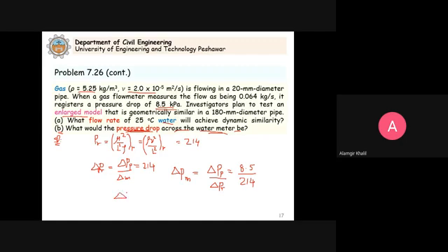So now this delta P, change in pressure for the model, this will be equal to 0.0397. So this is kPa, kilopascals, or this can be written as 39.7 pascals. So this is Newton per square meter. Clear? So this is how we solve these problems. Clear?